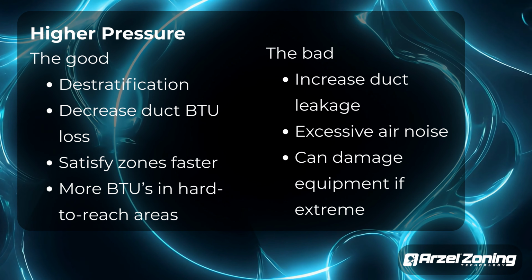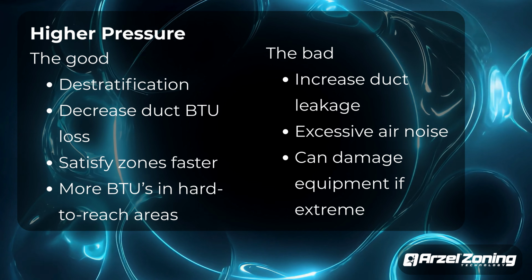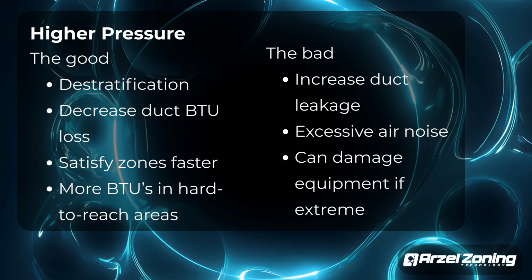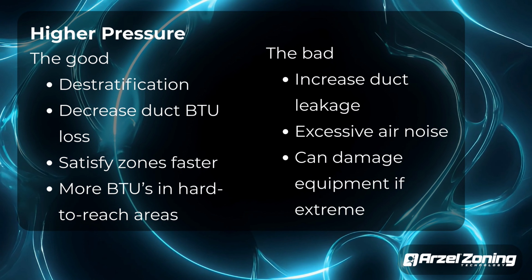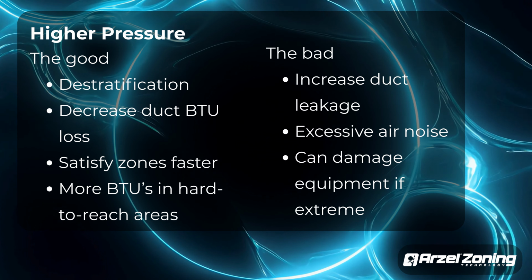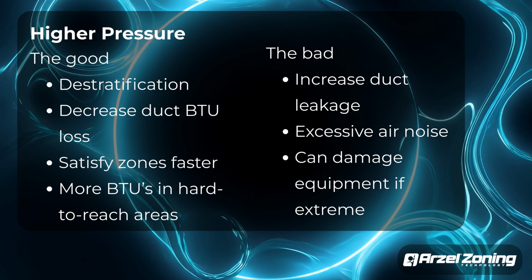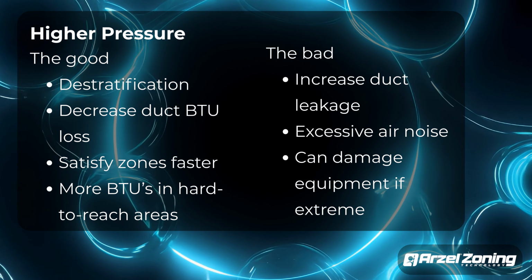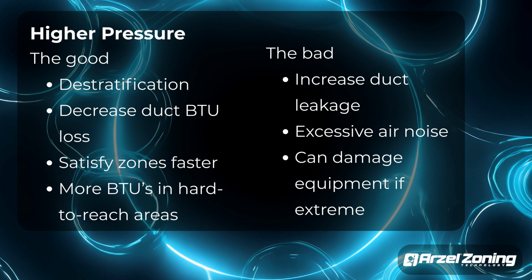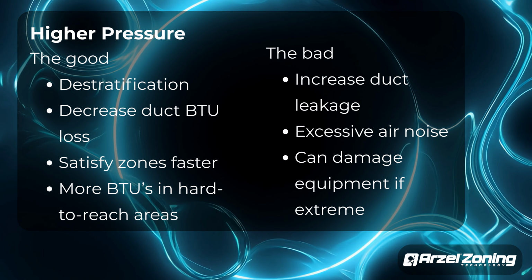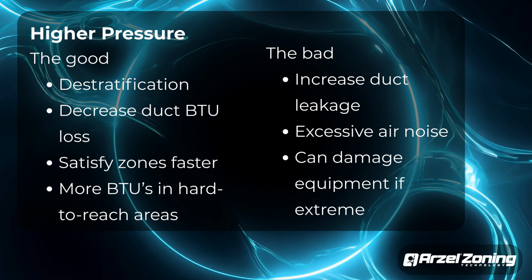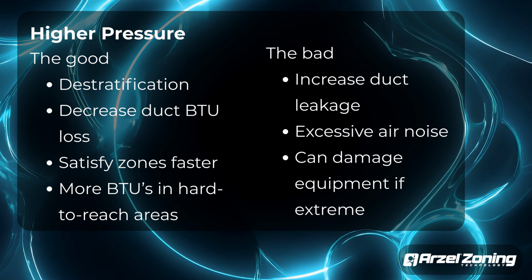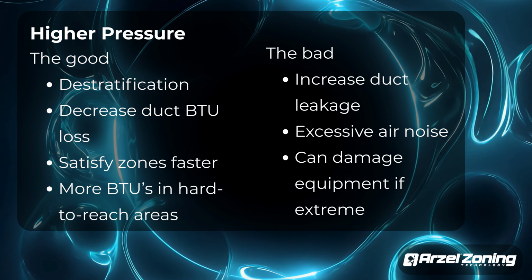Now the negatives could be if you have a lot of duct leakage and you increase static pressure, you're going to have a lot more duct leakage. One way to know that is if it's the middle of summer and it's 93 degrees and humid outside and you're in the basement and you want to go grab your hoodie out of the van because it's so cold down there, they have duct leakage. So be mindful of that. If you push the static pressure too high, you're going to have objectionable air noise, which we talked about. And then if you really overdo it, you're going to be pretty hard on your customer's equipment, and we don't want to do that.